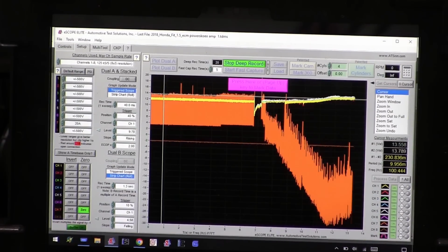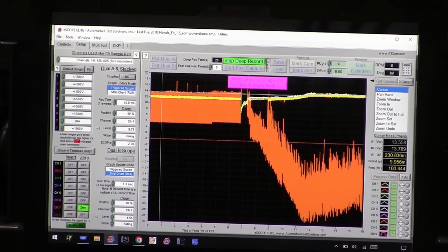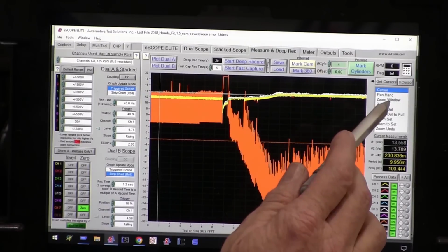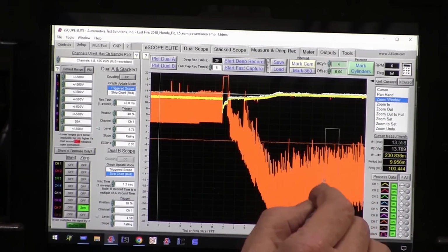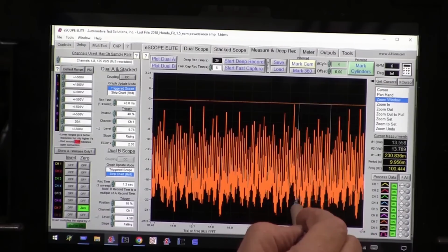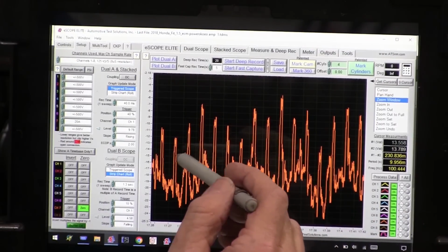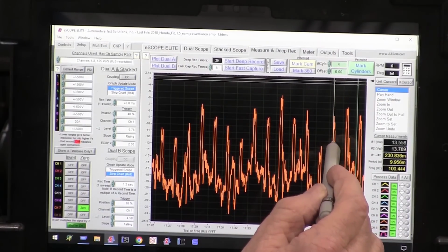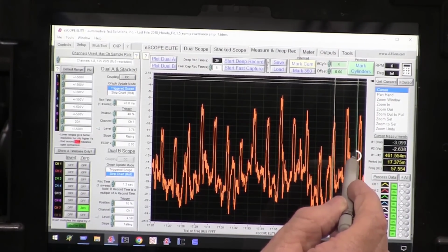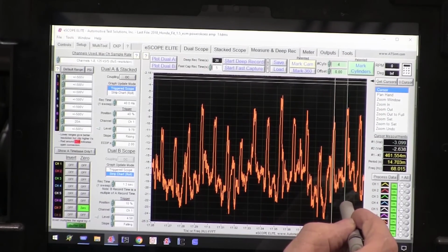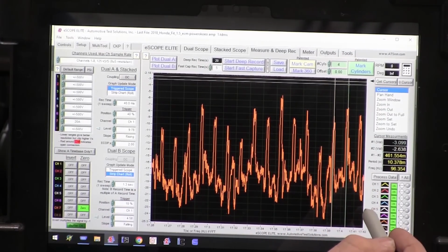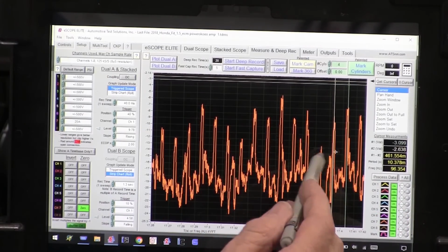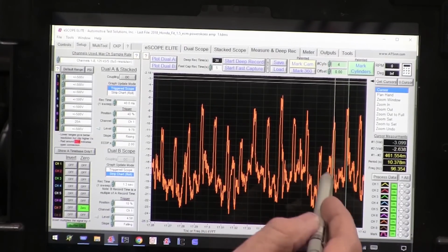Okay, so that's reverse right there. That's park. That's drive. Okay. Let's look at this. So we're definitely changing this pulse by changing the gear selection. Okay, we can see that the pulse has changed dramatically here. Okay, so I've still got about 10 milliseconds, but we're seeing that it's being controlled differently now than when just the key is on.